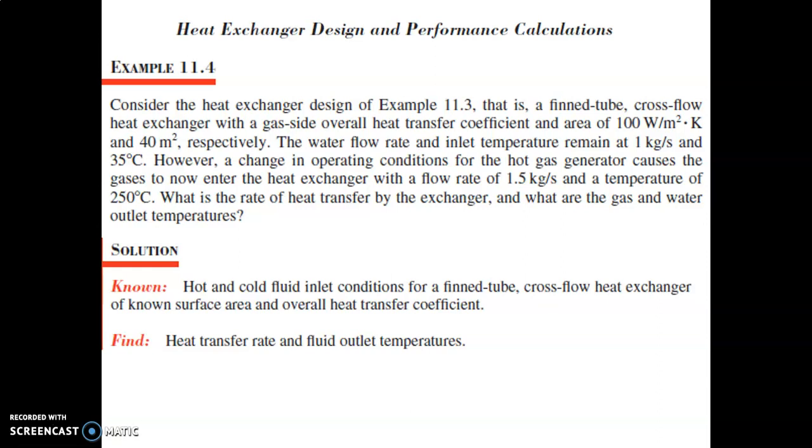150. So now from the question we can figure out that the question provides two mass flow rates and at the same time provides two inlet temperatures, one for the cold, one for the hot. The question also provides the area and the overall heat transfer coefficient. So from this data we are able to calculate the maximum heat by finding the C minimum from the cold and the hot, and we are able to use the table by using only the inlet temperature.